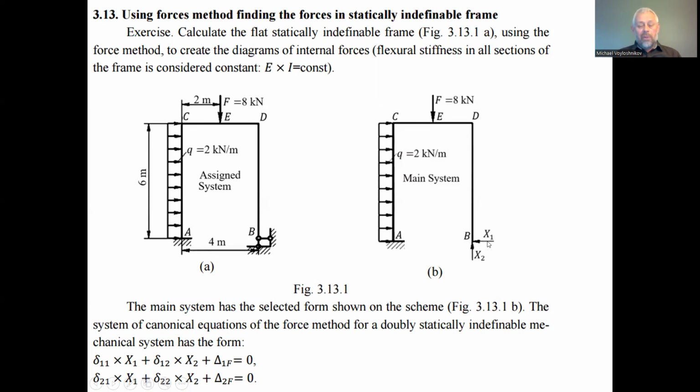These are not the unit forces; they will be unit forces when we determine the factors in the canonical equations of the force method to find these reactions, the magnitudes of x1 and x2. Actually, these are the reactions, not unit forces. Okay, so after determination of the main system, as indicated on the right, diagram 3.13b,